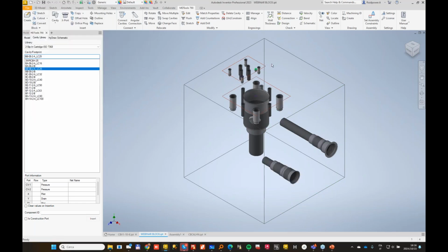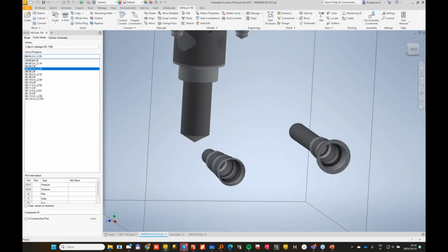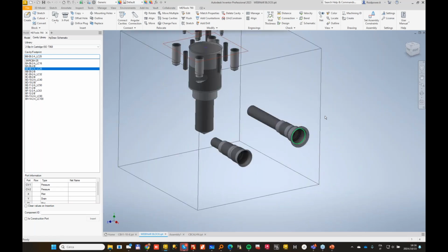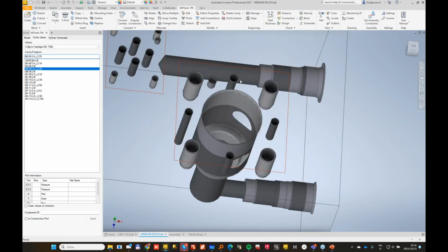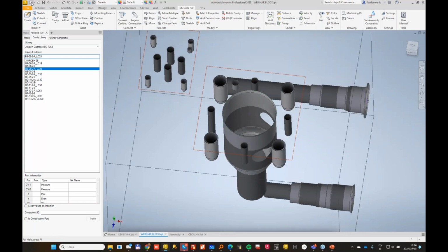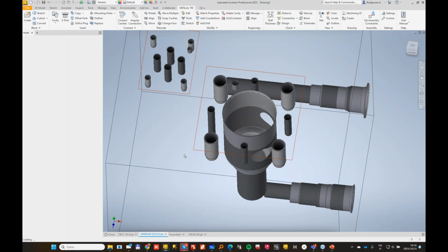So basically, while it's very simple for a cartridge valve to be assembled because it's a cylindrical surface and we just need a mating plane and an axis, the problem of surface mounted valves is that they require an orientation. So let me create a small view so I explain the rules for assembling footprints, and then we do practically.